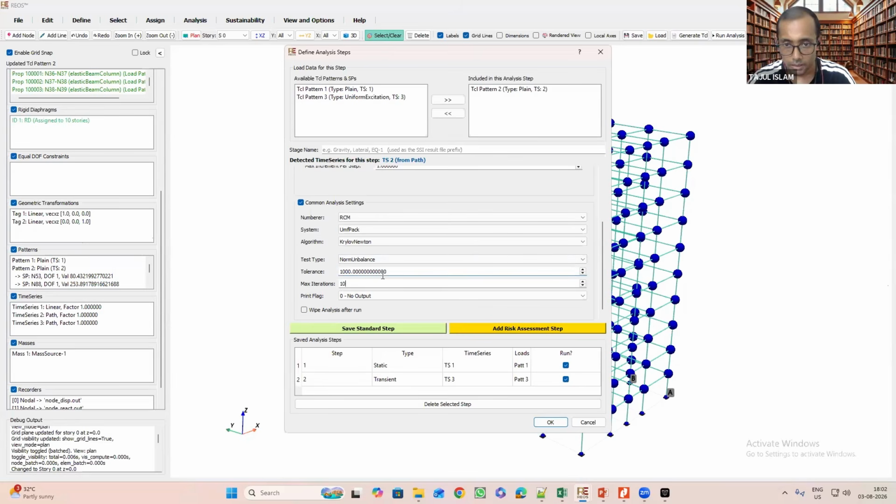This tolerance is actually a little bit tight. If your model is not satisfying this, you have to relax it a bit, so you increase this number. This is how you decide this parameter. But when relaxing, it should not be so high that your model diverges and gives you an incorrect result. It should not be that way.